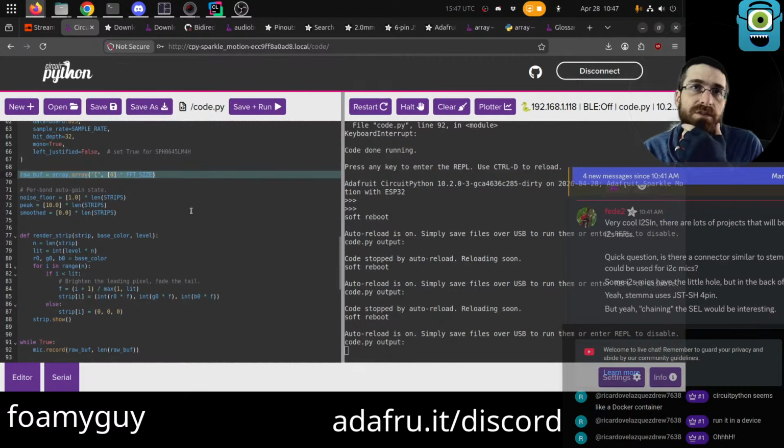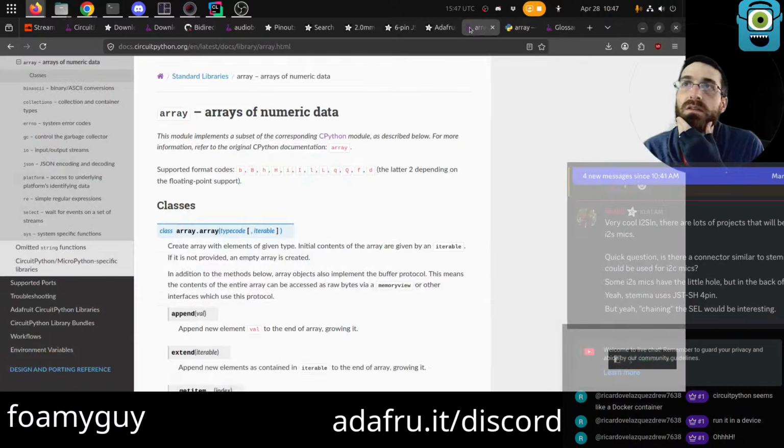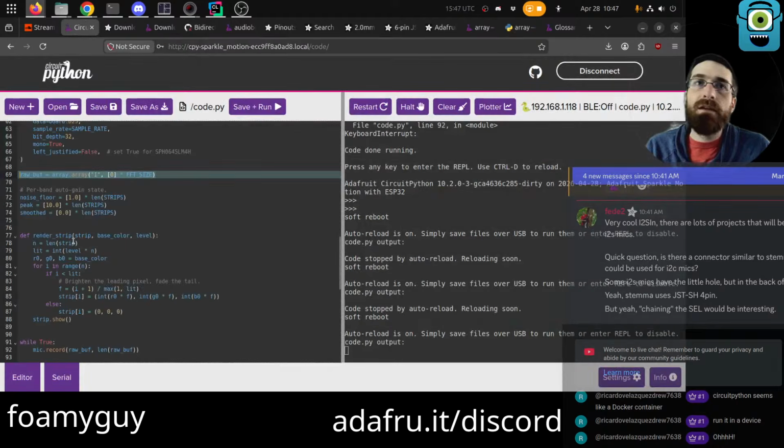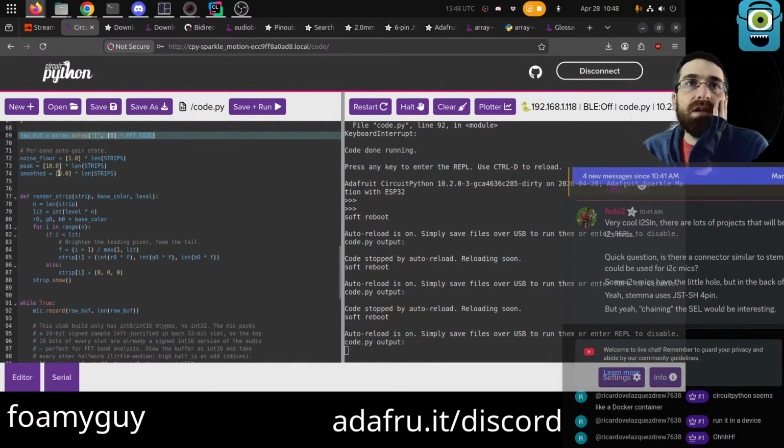So having this be 32 would make sense, but it was not possible on CircuitPython, I think. Presumably one of these would be for an unsigned long, or a float. It tried that at first, but it was not working on CircuitPython. So now it's got 16 bits, and I think it just uses 2 entries in the array. Although it is interesting this is not times 2 or anything.